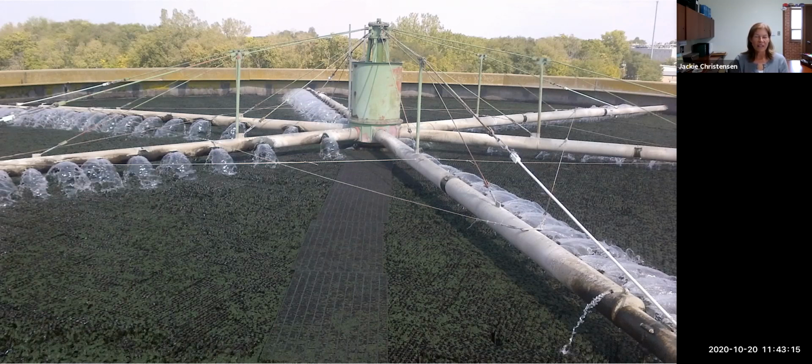There is some maintenance with this. Occasionally you'll have an overgrowth of algae on the top of the surface, and you'll get ponding. So we'll take the tower off either in the winter and basically freeze dry the algae off of it, or we can also take it off in the summer and just let the sun bake it and kill that top algae, and then it'll flush through.